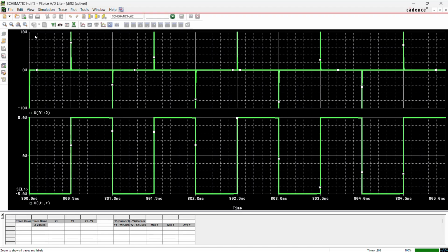That is within the range of frequency wherein it will differentiate properly. In that case, you'll get almost double the value as the output. So this is the only case where you get V naught greater than Vi. In all the other input cases, you'll get V naught less than Vi.